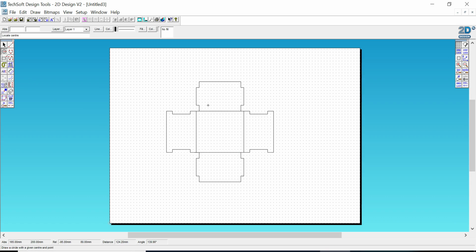Right, next thing I need a hole in the side of my box for the wire to go through. So the USB cable goes through into the inside of the box. That's all good. Okay, next thing, I'm going to put a little shelf. The little shelf is going to let me support the LED in the center of the box. I need a little space for the shelf to go in, so that's where it's going to fit into a little notch. And I'm going to make another notch like that, exactly the same on this side over here.